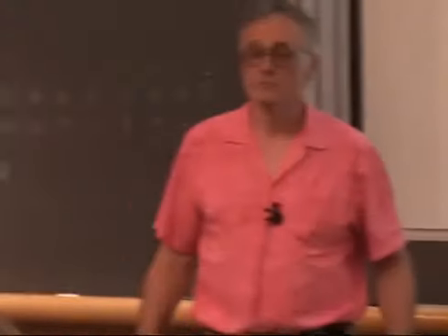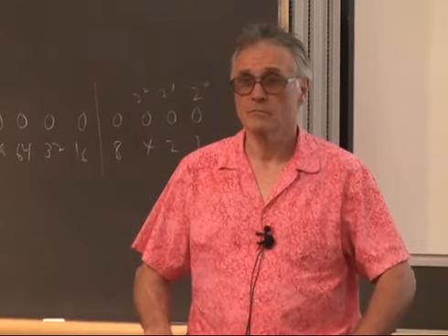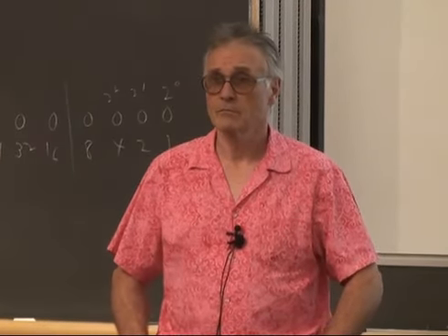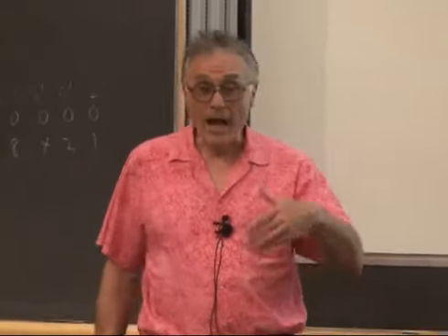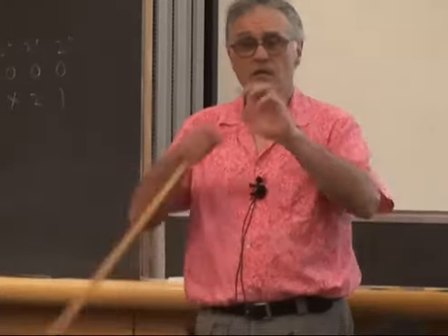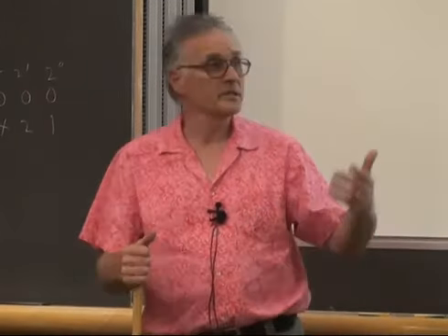Yes? Why not do those state switching when you're actually reading from the pins and then just pull that figure, and then have another for doing your actual logic? So you can arrange this any way you want. I happen to like to factor it into a low-level scanner, which does all the weird I/O bit twiddling to get a number out, and then a state machine that works on the abstract digit number without having to worry about the hardware. But it's up to you. You can mix them together if you want.